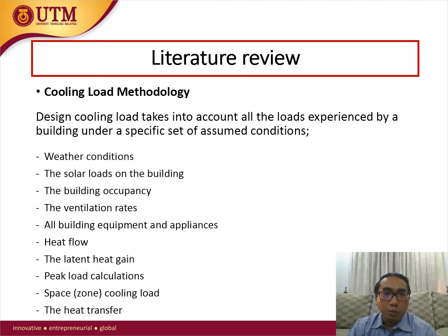The solar loads on the building are assumed to be those that will occur on a clear day in the month chosen for the calculation. The building occupancy is assumed to be at full design capacity. The ventilation rates are either assumed based on air changes or based on maximum occupancy expected. All building equipment and appliances are considered to be operating at a reasonably representative capacity. Lights and appliances are assumed to be operating as expected for a typical day of design occupancy.